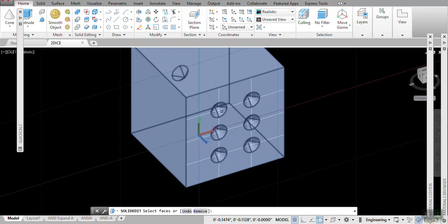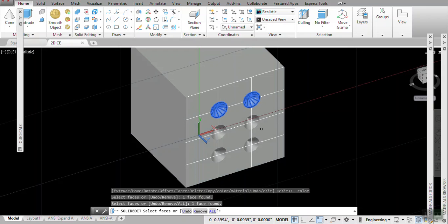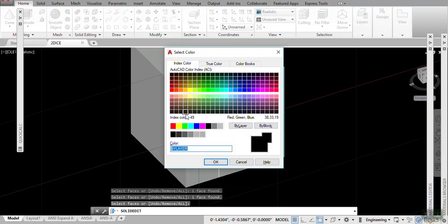There's no cone there and only the inside surface left. Click each one of them. Click and click and click, 6 times. And it highlights. Every time you click, correct the highlight. Enter key. And remember the color 19. You select the color 19. It's the critical color. Okay.